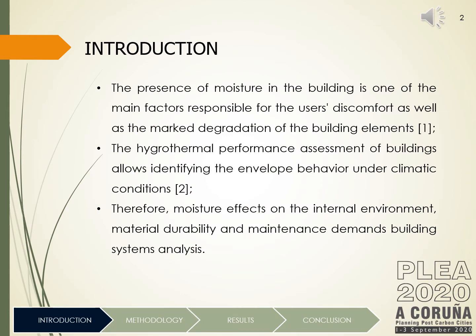So, as you know, the presence of moisture in the building is one of the main factors responsible for user discomfort, as well as marked degradation of the building elements. Water can also have other effects, such as freezing deterioration and loss of bonding between layers due to vapor condensation and interfacing between building layers. In addition, there are indirect effects such as chemical attacks on natural stones, corrosion of concrete elements, among others.